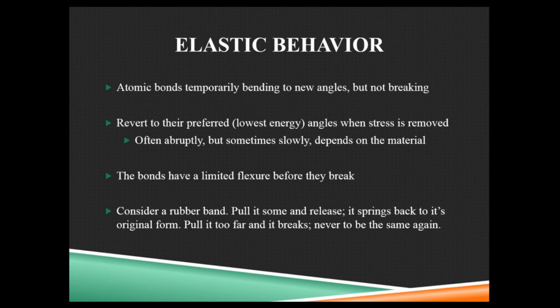Well, sometimes when you apply stress, they get flexed a little bit. If the bonds bend to new angles but don't break, and the molecules aren't shifted past each other, again, the connections between the molecules are stressed, or strained rather, without breaking, so just bending to new angles. This means that when you remove that stress, since no bonds broke, they will revert to their preferred angles.